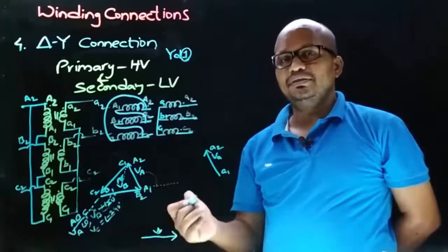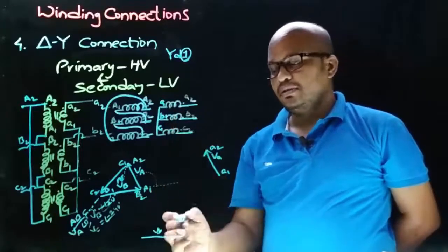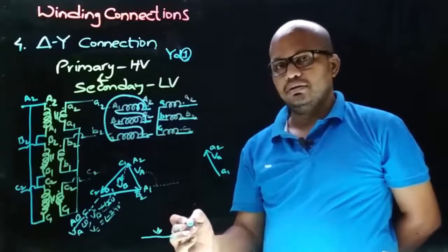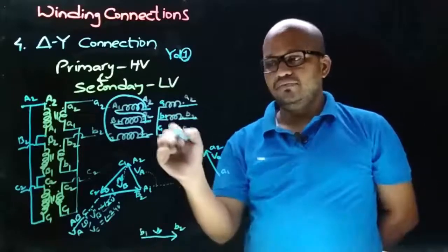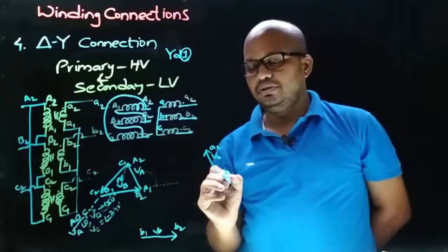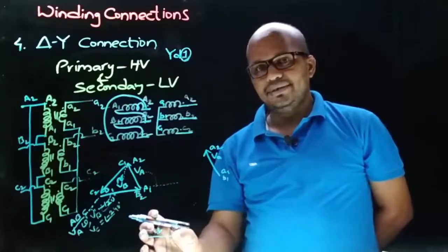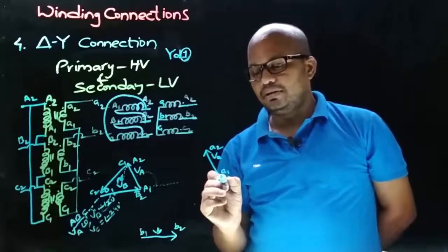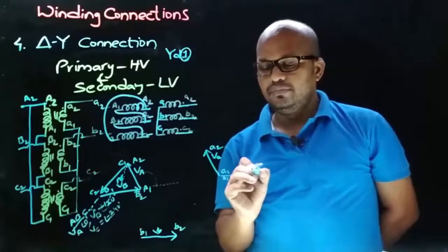And now we need to decide the terminals of the VB phasor, and as the connections are taken on dot end terminals, the arrow will point towards the dot end terminal. Therefore this will be B2 and the other end will be B1. Observing the winding connection, to A1 there is the B1 connection. So here to A1 there will be B1. So now place this phasor such that A1 is having the B1 terminal. Therefore, this will be the VB phasor.